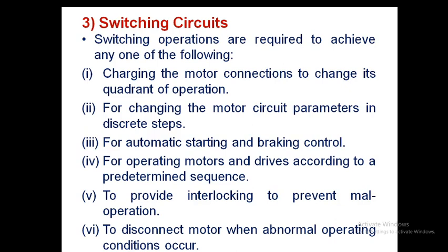Because of an improper firing sequence, your devices will malfunction. Instead of turning on at 1 second, if it turns on at 0.9 second, both the switches in the same leg of the converter will turn on and completely short circuit the devices. Such malfunctions need to be avoided by giving the proper switching circuits.